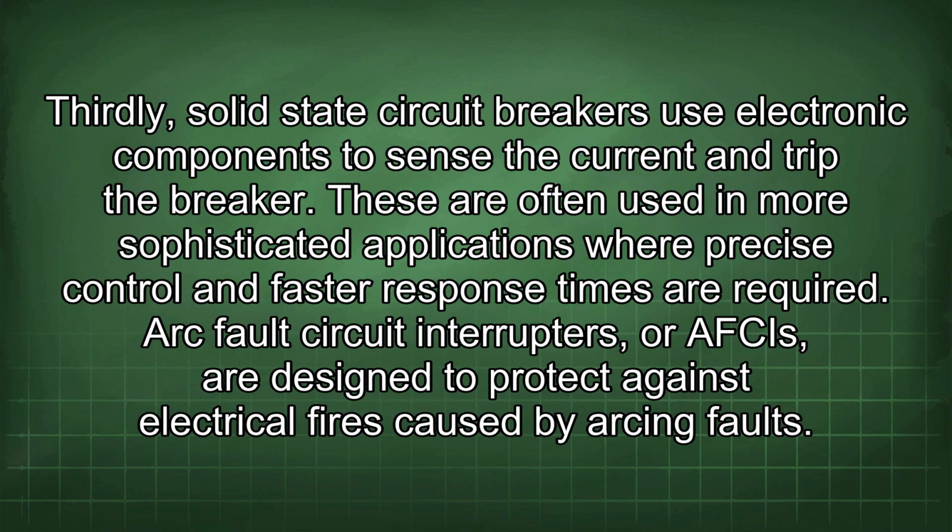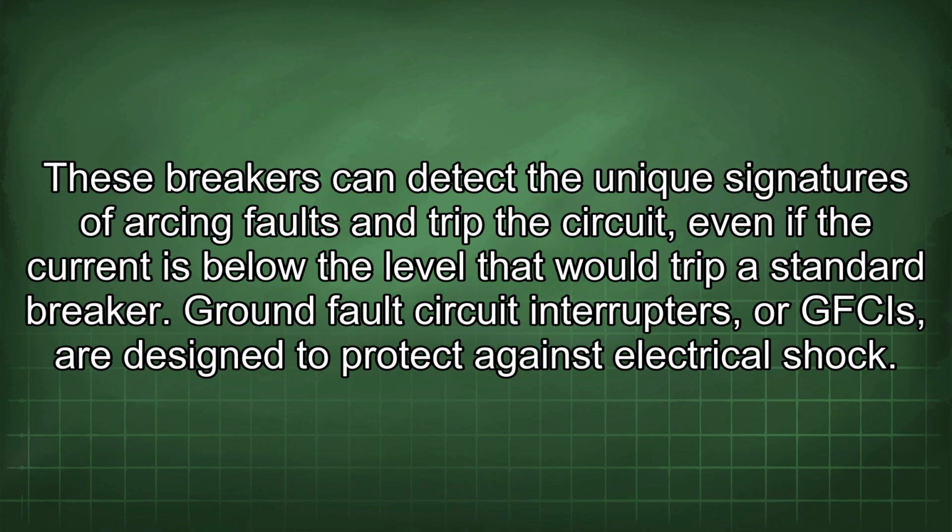These are often used in more sophisticated applications where precise control and faster response times are required. Arc fault circuit interrupters, or AFCIs, are designed to protect against electrical fires caused by arcing faults. These breakers can detect the unique signatures of arcing faults and trip the circuit, even if the current is below the level that would trip a standard breaker.